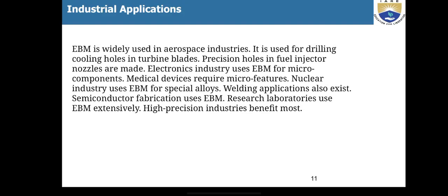Industrial applications. EBM is widely used in aerospace industries. It is used for drilling cooling holes in turbine blades. Precision holes in fuel injector nozzles are made.